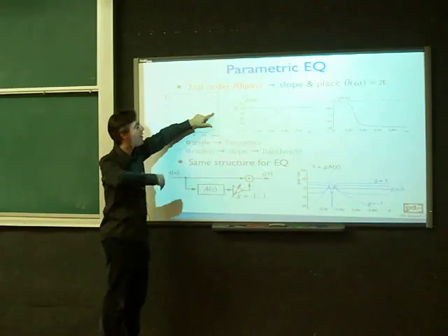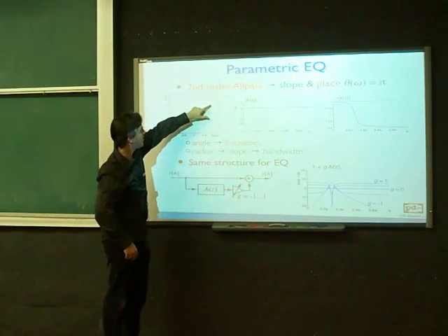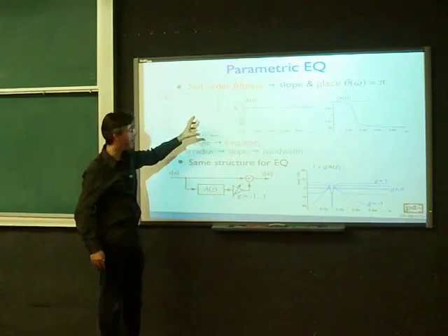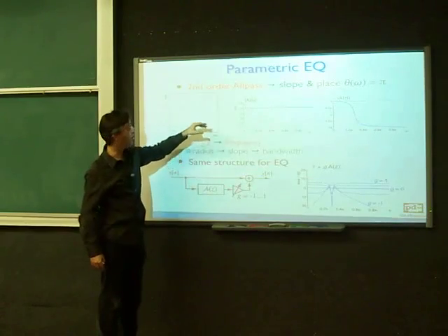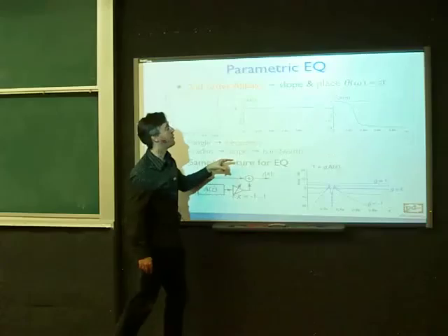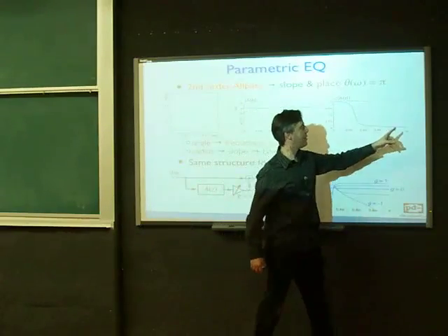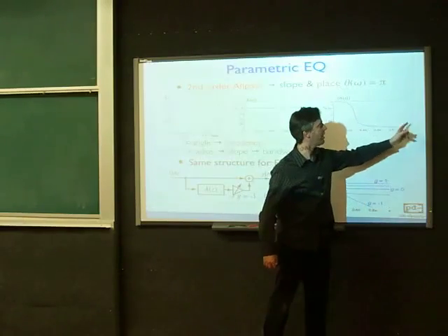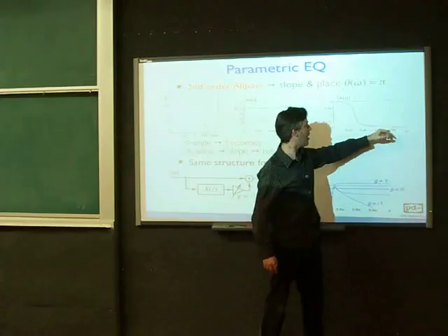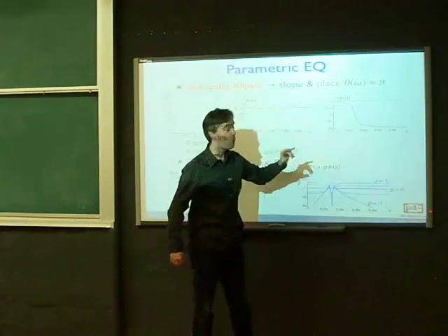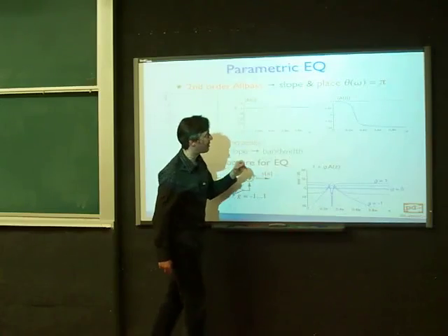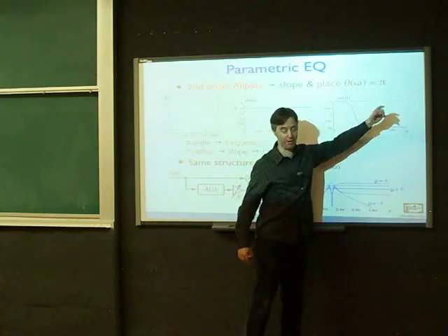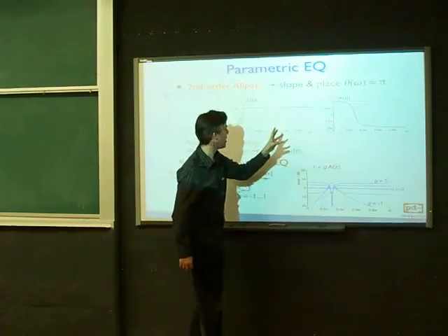They'll sort of go up and it'll go down. But the poles, you started off here and you sort of wound your way all the way around. So the poles have accumulated a total phase of 2 pi per pole, which means that for omega equal to 2 pi over here, the total phase change is 4 pi. And it's symmetric. So the total phase change at omega equals pi is 2 pi. Whereas on the previous one, where we only had one pole in the middle, the terminal phase was pi, was like 180 degrees. Now it's 360 degrees.